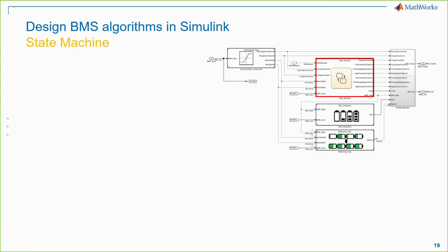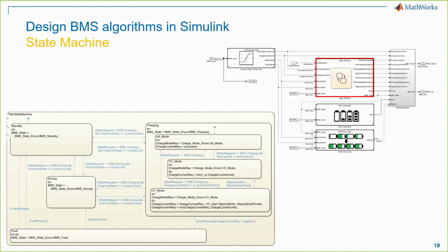Moving on to the BMS state machine, we have a dedicated software component that manages different operating states of the entire battery pack, including fault detection and contactor management. We use Stateflow to model different states and transition conditions between them.